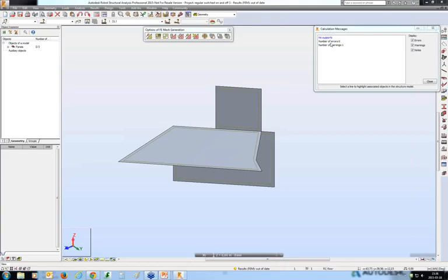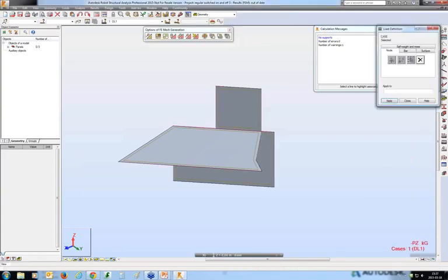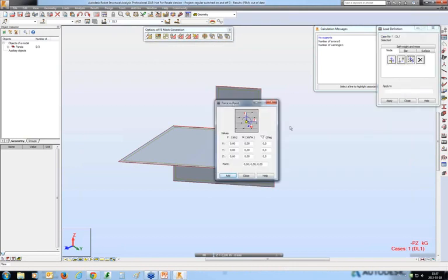Okay, so if you define the node in which you want to enter this point load and you remesh the panel, it will be recognized. But if, for example, you do not want to mesh your model again, you may select the option force in point, where you only give the coordinates of the location of the force, and this force will be distributed to the panel even though no node of the mesh is generated at the location of the force.